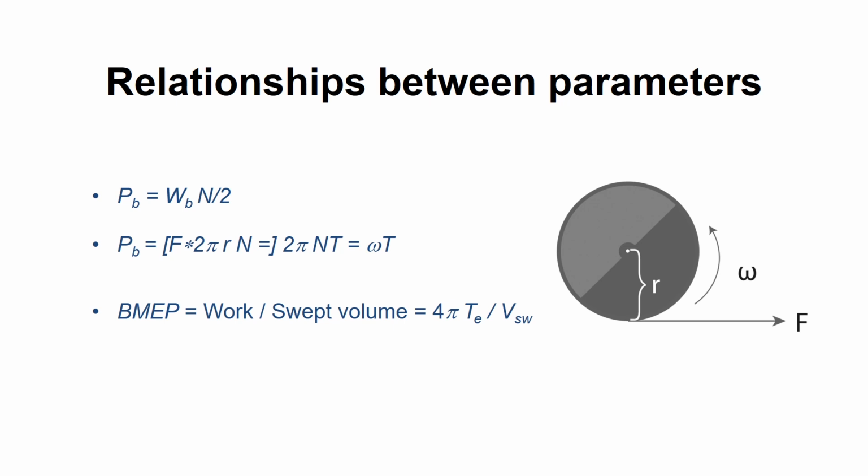The reason there is a maximum load or amount of work an engine can produce is that it is about how much fuel you can burn during a cycle. And combustion is a process that needs not only fuel but also air. There is no problem to add more fuel, but air is restricted by how well the engine breathes. And a consequence is that the maximum load of an engine is determined by how much air you can get into the cylinders. So, if you want to increase the amount of work an engine can produce, you have to supply more air into the cylinders, and this can be done using a turbocharger.